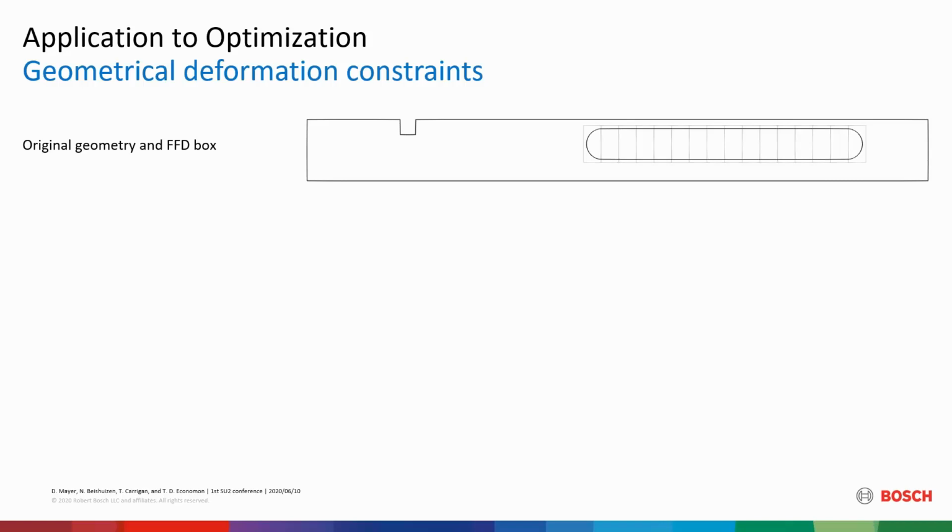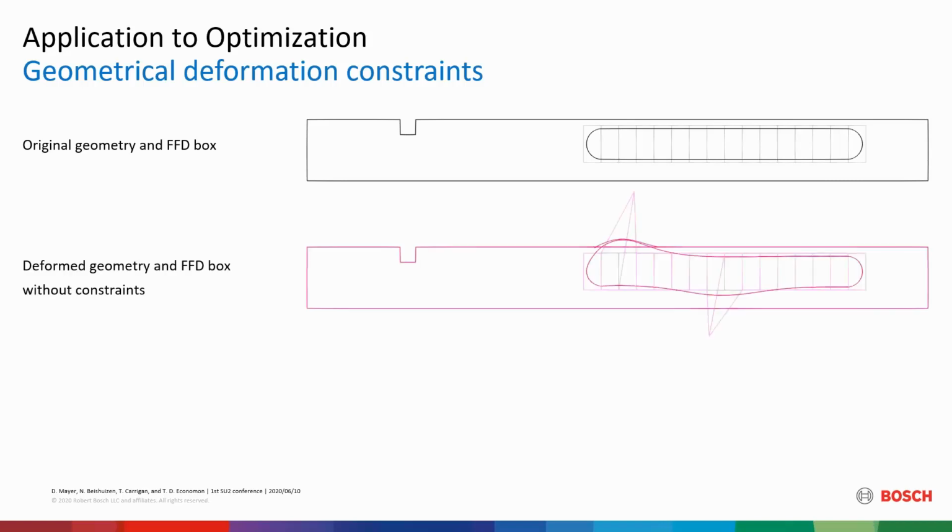This can result in a situation where the heat exchanger geometry intersects with the boundary of the simulation domain, which is something that cannot be handled anymore, and we need to avoid that. Furthermore, we found that the current implementation of SU2 lets you limit the deformation, but it's, let's say, non-optimal, or it's very complicated to use.